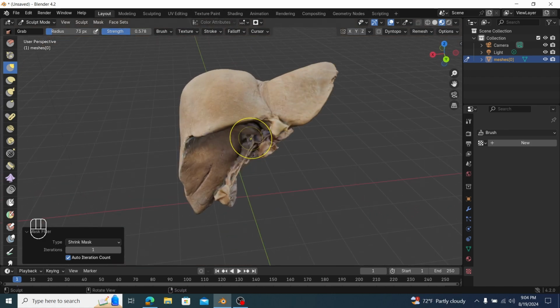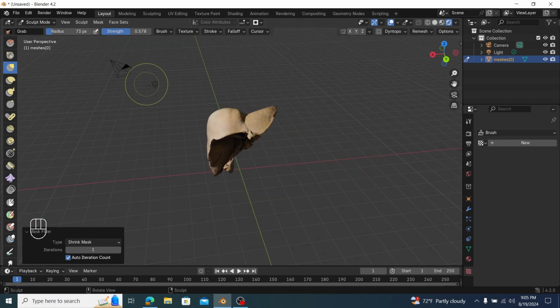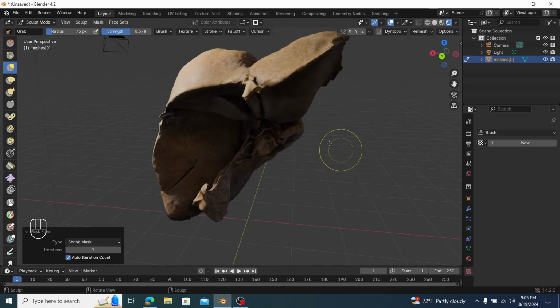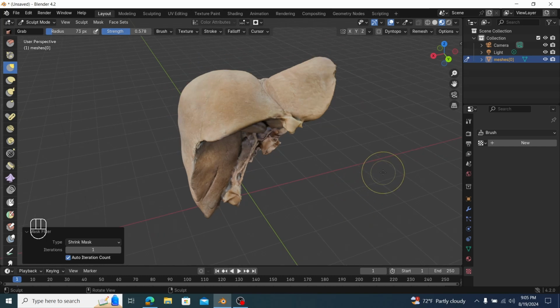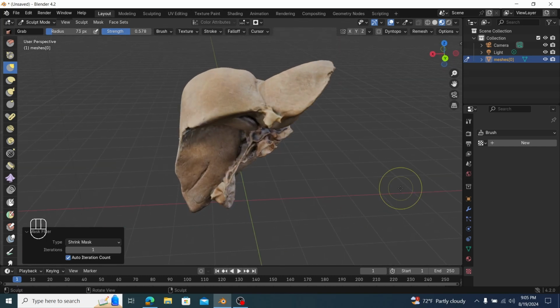When we're deciding between different views, we can choose between the material preview view and the rendered view. The difference is that the rendered view also incorporates the environment and lights on the rendered image, whereas material preview only shows the texture. For example, in the rendered, we have a light source over here that's casting light, which also results in a shadow. In the material preview mode, we don't have that light source casting a shadow.